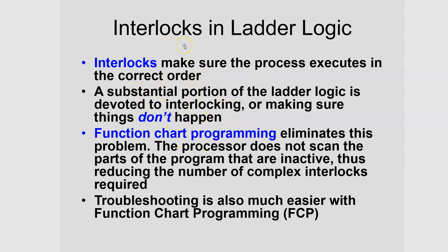So for example, let's say I have an elevator motor, a dual motor that can either raise the elevator up or, with another button, send it down. What I don't want to happen is for both parts of the motor to energize at the same time, up and down. That can cause an issue. And so you can have an interlock. You can have circuitry that guarantees that you can either go up or down, but there's no way that both conditions can happen.